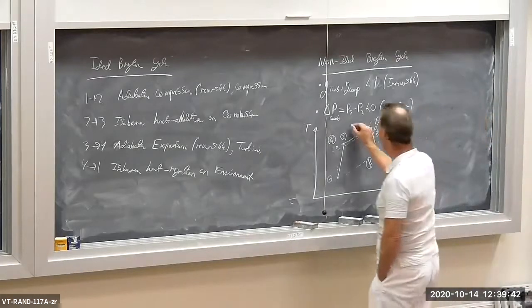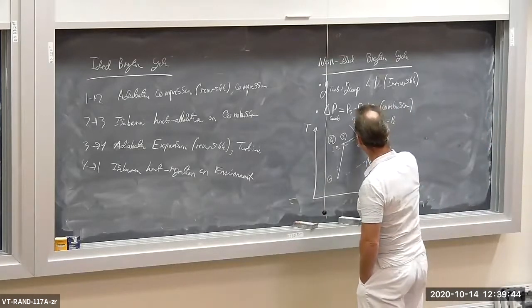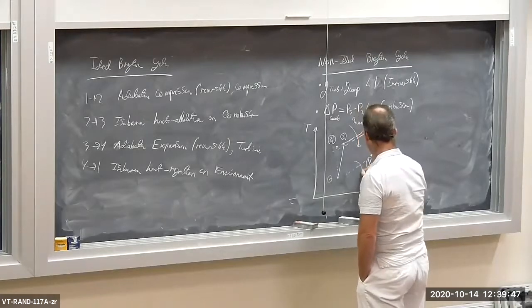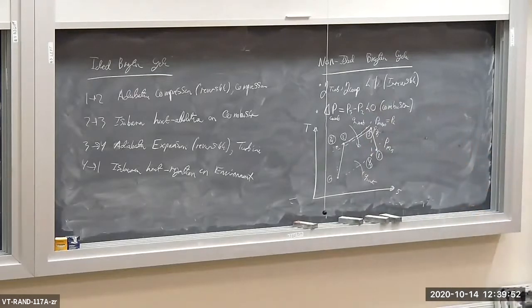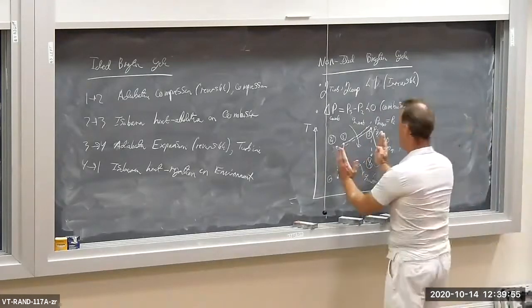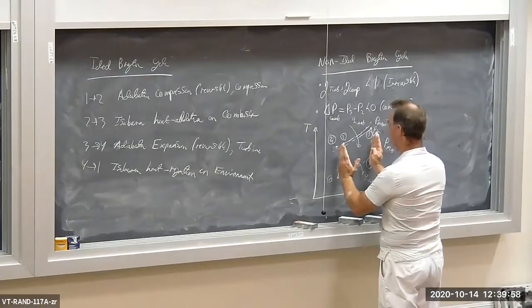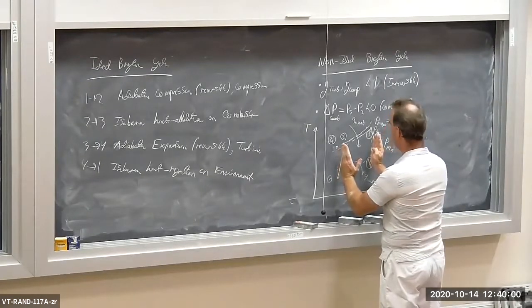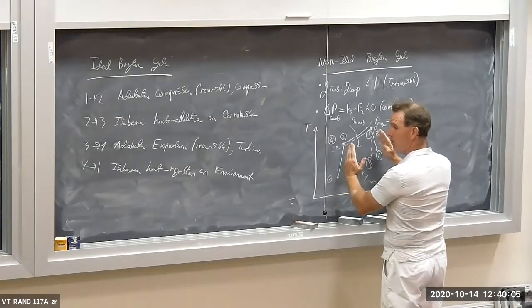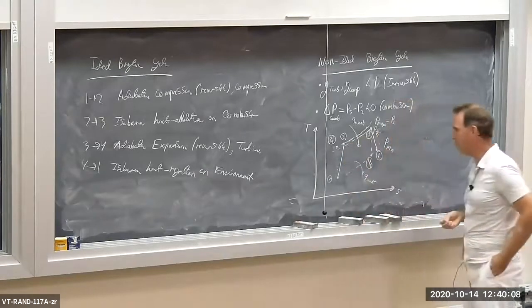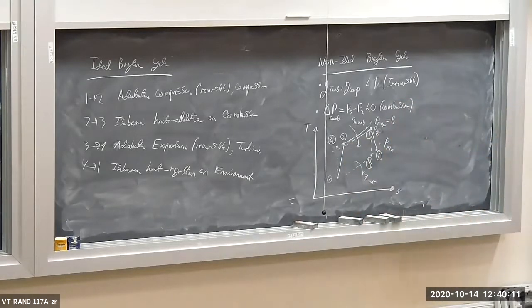So we have the heat addition process going on here in the combustor, Q combustor, and then we have the heat rejection process going on there. So the ideal process would have vertical lines for the compression and expansion process in the compressor and turbine. The real processes have a delta S because they're irreversible. And then we maybe have a pressure drop in the compressor and the combustor. So that's what the TS diagram looks like for a non-ideal Brayton cycle.